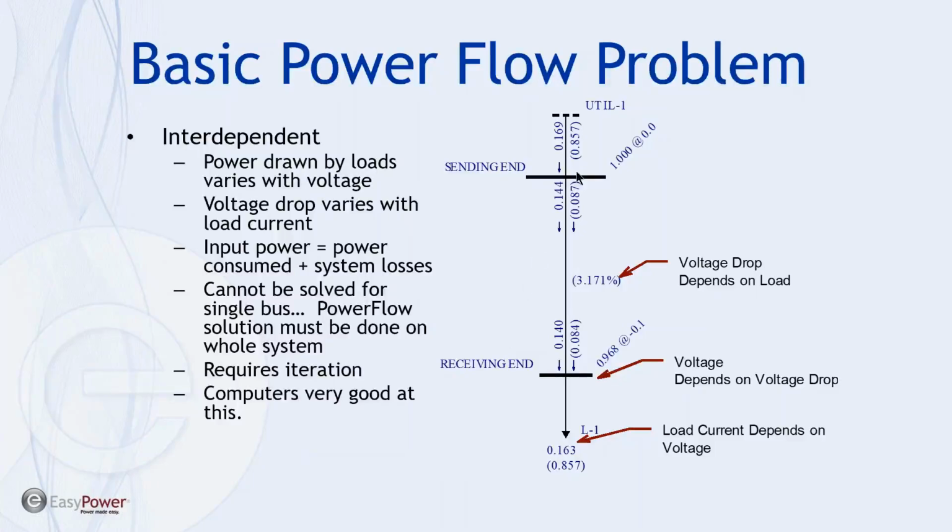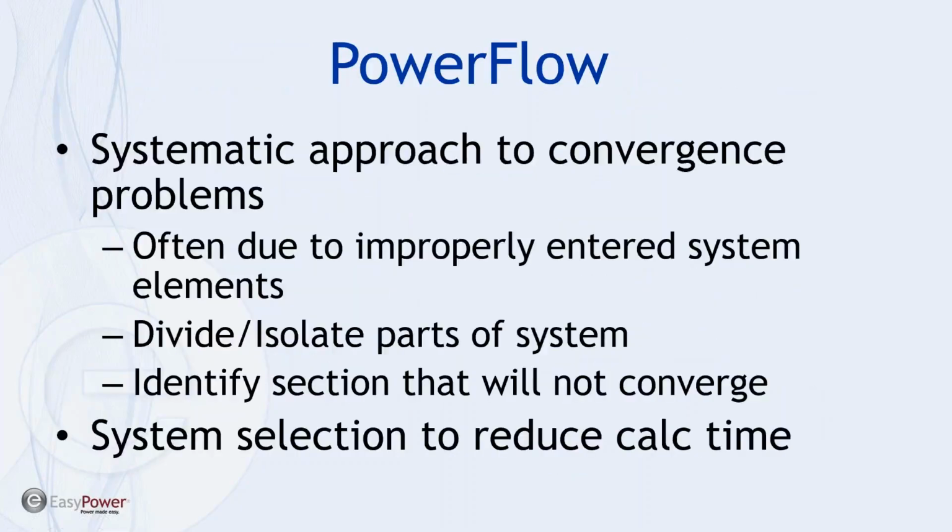Because these are vector sums, you assign some value to start with and then converge on a solution that you can control in EasyPower. The whole purpose is to have a result that approaches a convergence point that's similar to what our real system looks like. In applying that to a larger system, we may have some problems with the convergence.